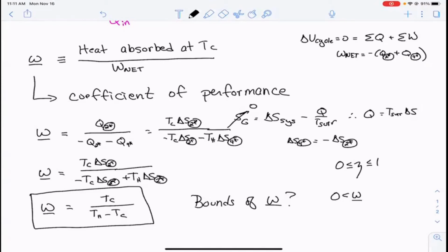Or there are parts of like Minnesota and Wisconsin. They're in those types of places. Heat pumps are extremely common because they're very efficient when you have small differences in the temperature. Whereas in a place like South Carolina, where it's 4 million degrees in the summertime, a heat pump is really not a smart investment most of the time.